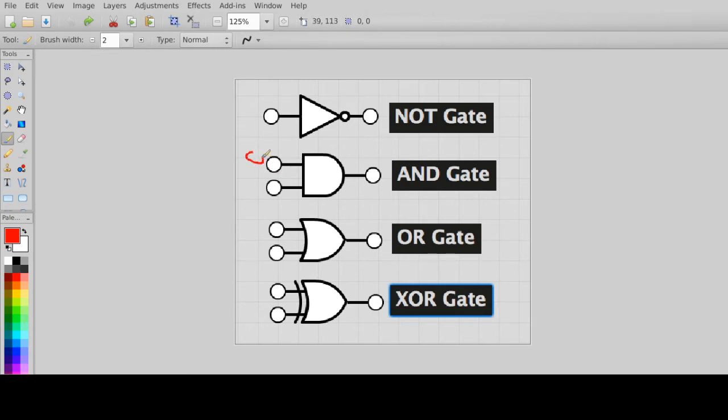If I feed one of them a 0, so that's going in there, and I feed a 1 on the bottom here like that. Well, what does AND do? Only if both of these are 1s will you get a 1 out. Well, one of them is a 0, so you get a 0. In other words, it's a machine which does exactly what logical AND does. So you feed it a 0 and a 1, and a 0 comes out.